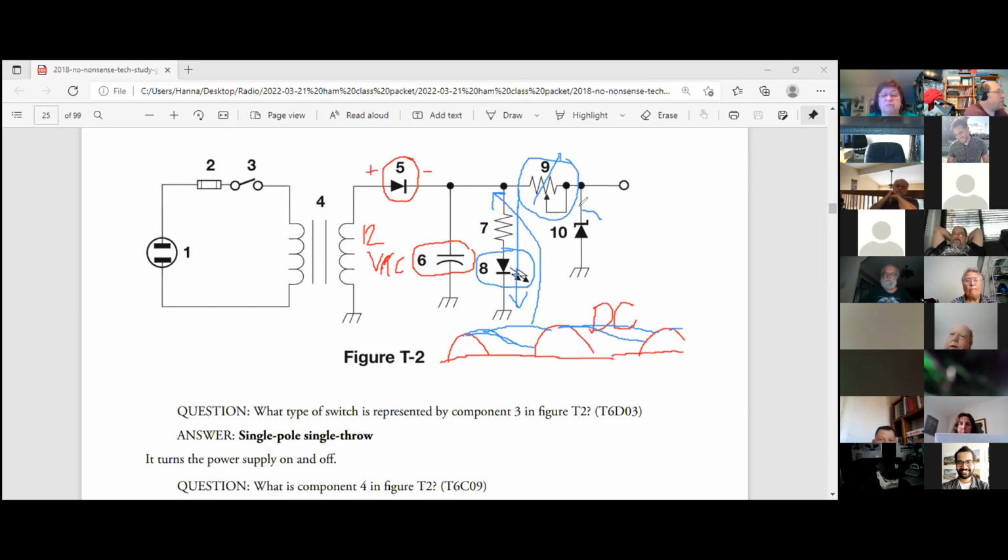And remember I said that every diode conducts only in the forward direction? Well, for every rule, there's something that goes against it. This is actually called a Zener diode. A Zener diode is a backwards diode that has a voltage reference. And what this basically does is say that I am picking my diode to say that I'm going to operate at 9 volts, and anything above 9 volts, I'm just going to allow to go down into the trash. I'm just going to basically cap the voltage at 9 volts.